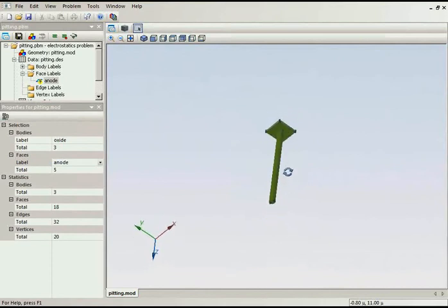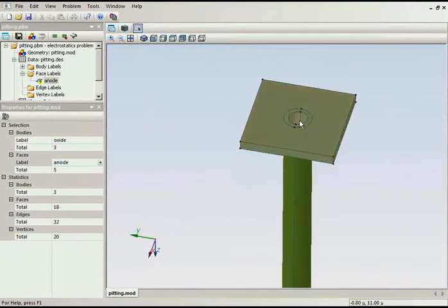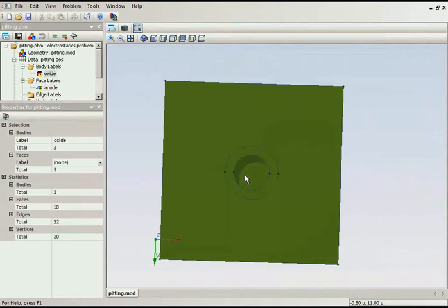So on this surface, I specify the anode foil potential. And on this side and inside I have the electrolyte. This side is in contact with electrolyte, so I should specify the cathode electric potential here, here and inside at the bottom. This would be the cathode.